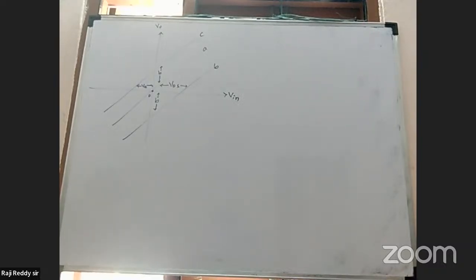Only the curve A line is passing through the origin. The voltage VOS, which would have to be applied in order to obtain zero output voltage, is called input offset voltage.